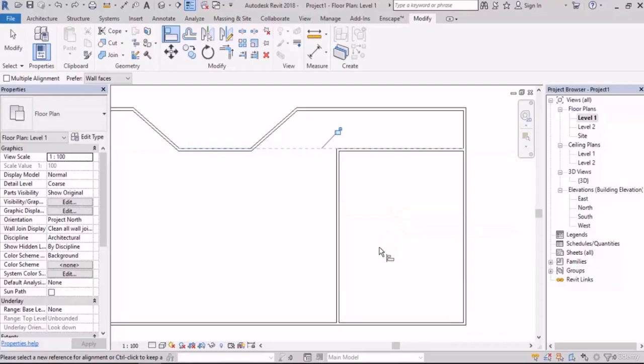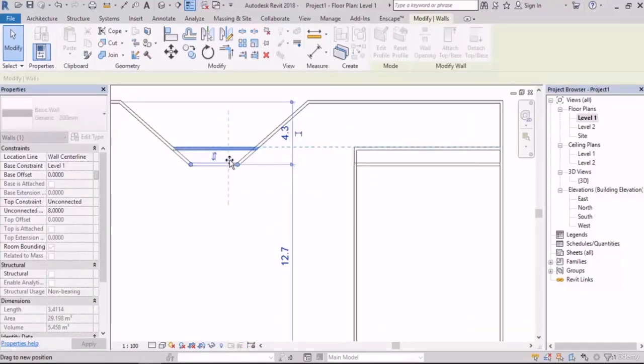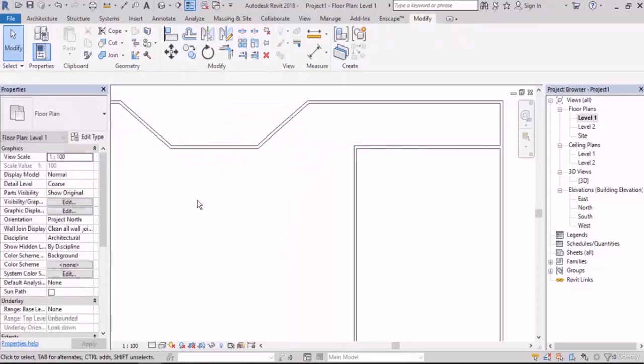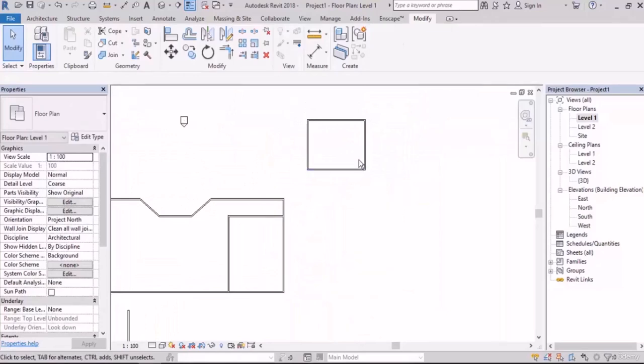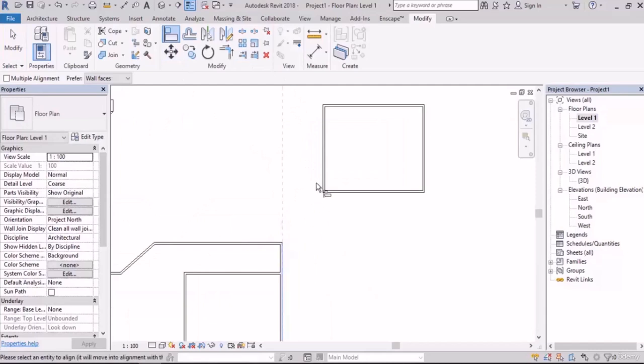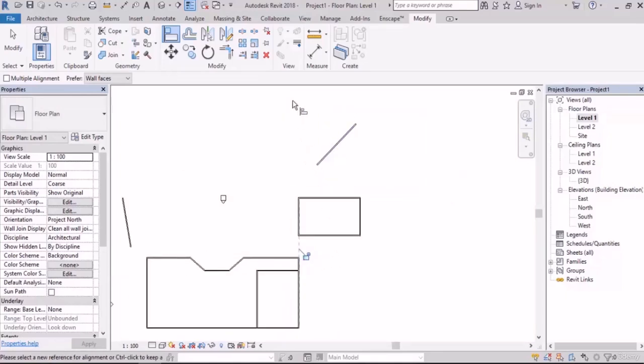And you can see a lock there, don't do anything to that. But if you want to know, if you click on it, the direction of these two walls will be locked. So if I drag this one down, that one will come with it, but don't do anything about that. For example, I want to align this wall to the previous design we had. So I choose align and this one and the one from inside. And then they are aligned and it's different.